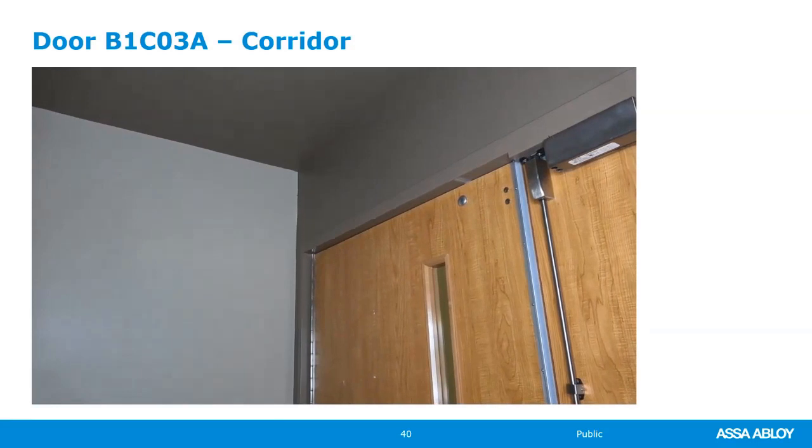On a double egress door, the astragal, the overlapping, this isn't an overlapping astragal, it's a brush astragal. But even if this were an overlapping astragal, because the doors swing in opposite direction, you wouldn't have any issue. There wouldn't be any deterrent with the overlapping astragal to inhibit the free use of either leaf. You still can use either leaf.